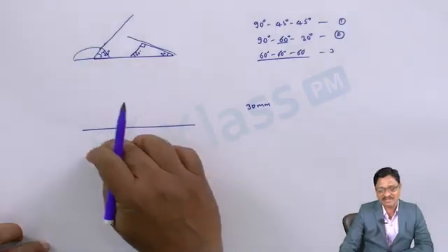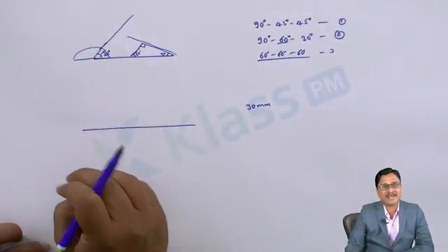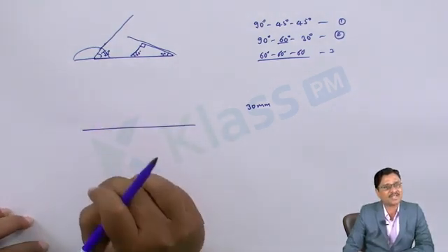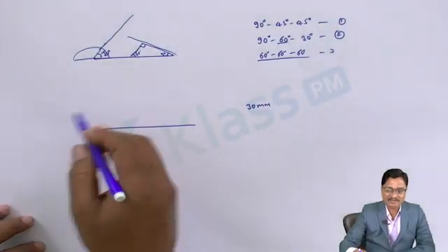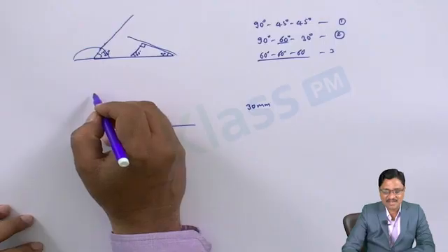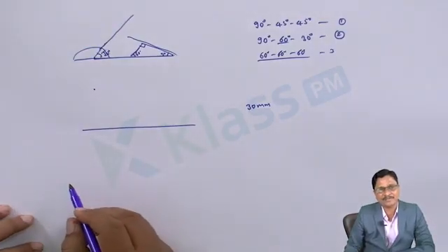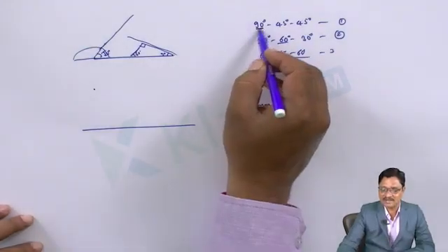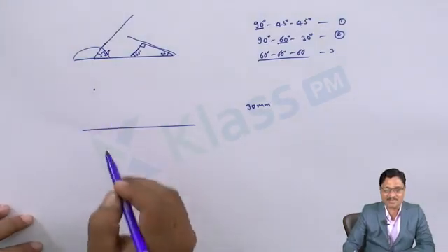So by using the scale, you can place the 30 mm, but it may not give the guarantee that it fits exactly the same gap of 30 mm everywhere. So for that, we know that we may use the protractor perpendicular to the line. By measuring 90 degrees, I may place a point at a distance of 30 mm. Otherwise, by using the set square at 90 degrees, by placing the set square, I may fix the 30 mm point.